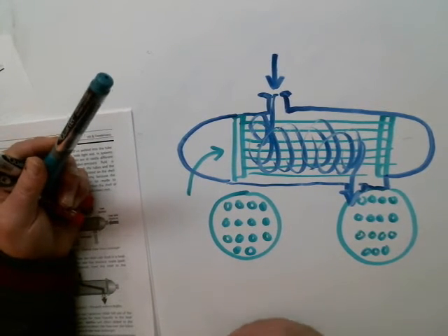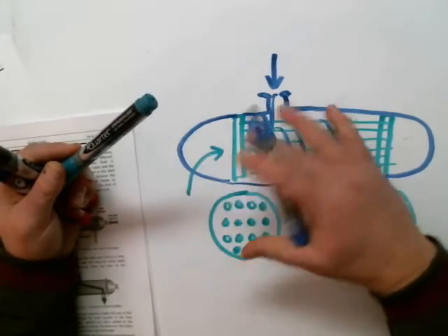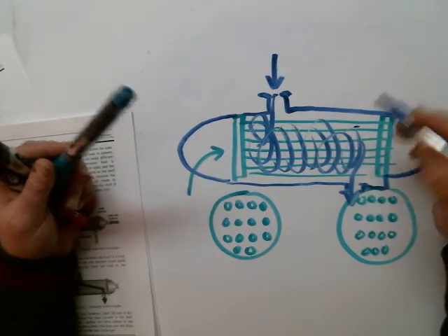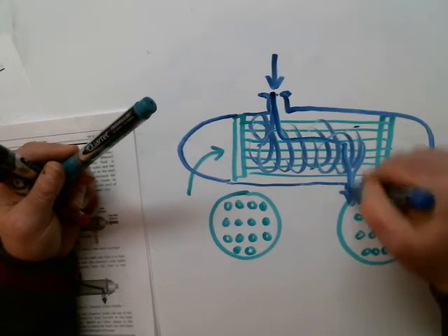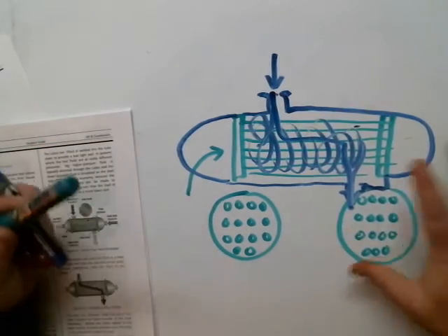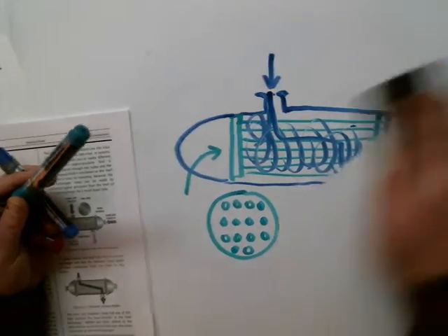So I would transfer energy from the hot fluid to the cold fluid. The key is I really want to keep them in contact with one another via these tubes and shell. If I just short cycle real quick, I'm not going to get good heat transfer. So we need to do something to promote contact time within the shell of that heat exchanger.